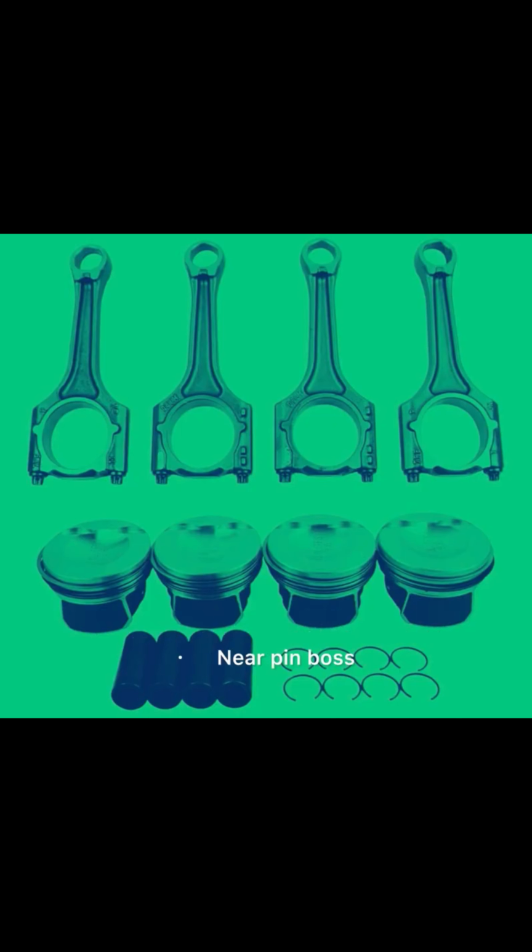14. List different types of connecting rod designs. Straight, offset, straight cut, bias cut. 15. How do manufacturers align the connecting rod caps? Fracture, sintered metal, dowel, shoulder on rod bolt.